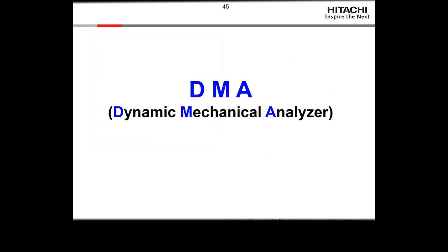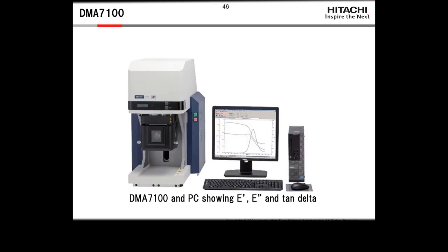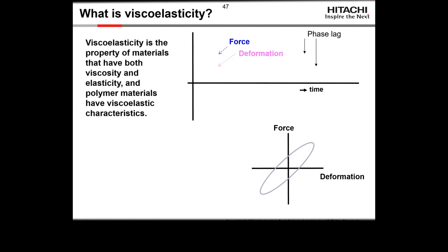So our last thermal technique and our second to last topic is dynamic mechanical analysis. Here's a DMA, and if you notice here, there's like a little window, and this is for the real view system, which we'll talk briefly about next. And what the DMA is going to give us is a storage modulus, a loss modulus, and a tan delta, which are on this.